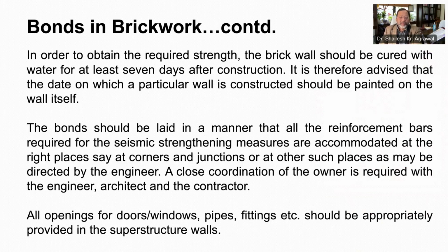Also, all openings for doors, windows, pipes, fittings should be appropriately provided in the superstructure walls. One of the important things is the requirement of seismic strengthening if the location falls in a seismic zone, and accordingly structural design and construction should incorporate the same.